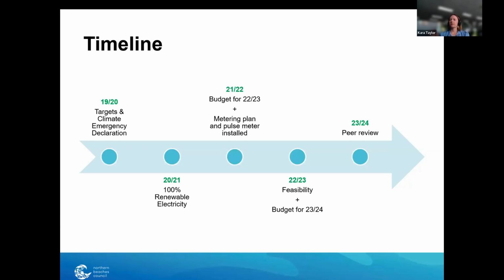So the feasibility that we did, we broke it up into 2 stages. The first stage was looking at electrifying our gas assets to reduce emissions and getting a roadmap for exactly if we were going to do it, what that looked like and how long it was going to take us. But also importantly, sticking on energy efficiencies, because you've already got a whole bunch of fancy engineers looking throughout your whole system. You're about to increase your electricity usage on site. So it makes sense to also get them to give you recommendations for how you can reduce energy for your other equipment on site. So the electrifying the gas assets and energy efficiency.